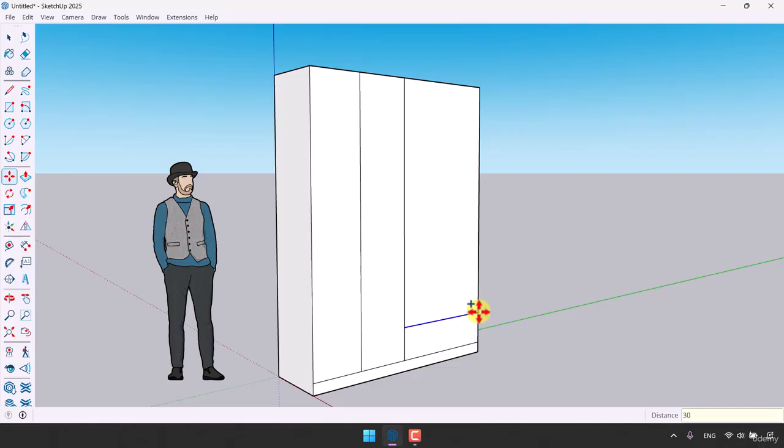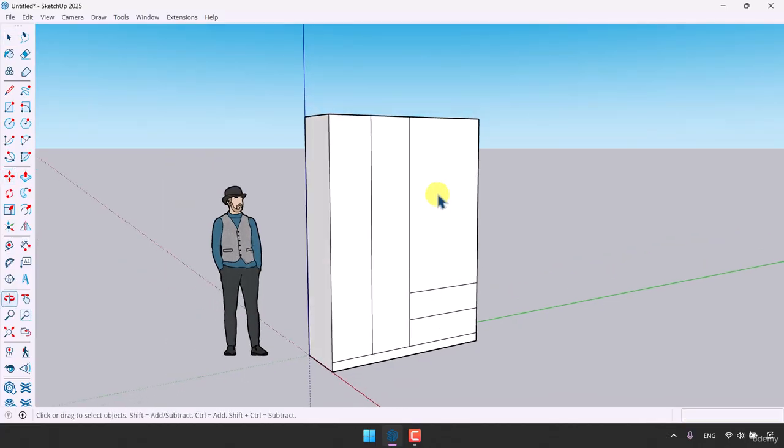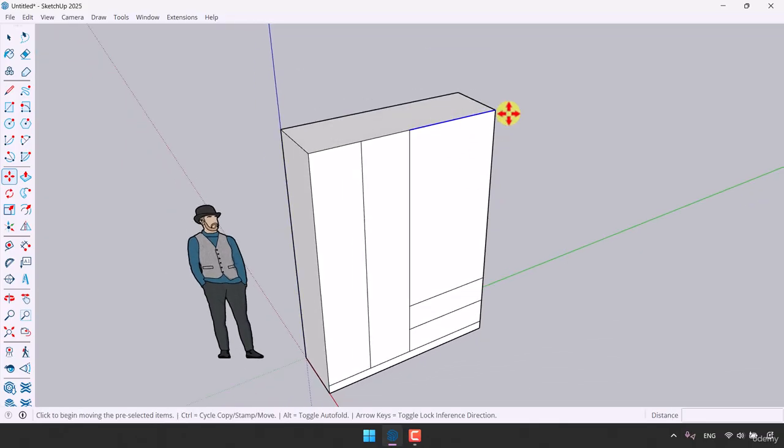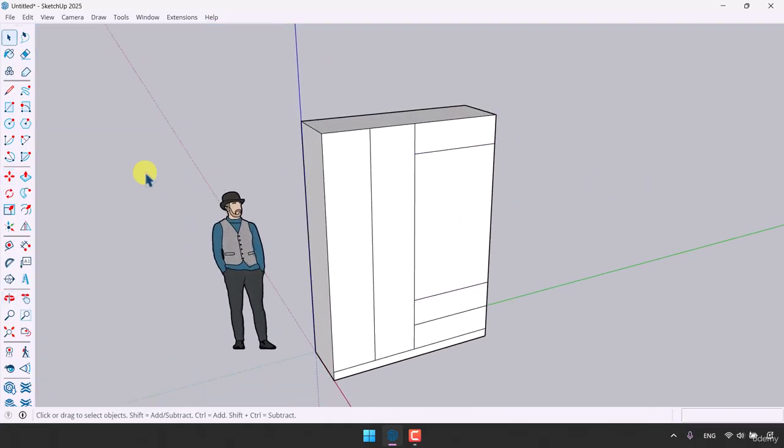And now I want to repeat it 2 times. So I'm going to type 2x here. And now I want to divide and manage this face. From the upside, I'm going to take an equal copy with the downside. So I choose this line, press Ctrl and take another copy at 30 centimeters. Everything is done for me. Now I'm going to click on the Align option and draw my last part of dividing like that.